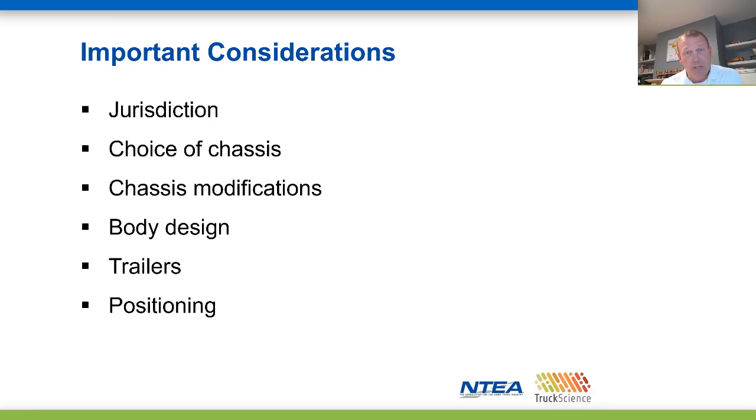Then adapting your body design to the payload that you're carrying is crucial, so experimenting with materials, weights, and dimensions. And then adding a trailer can increase payload significantly, as we saw, if that suits your operation. And finally, testing the various components in different positions to come up with optimal placement.